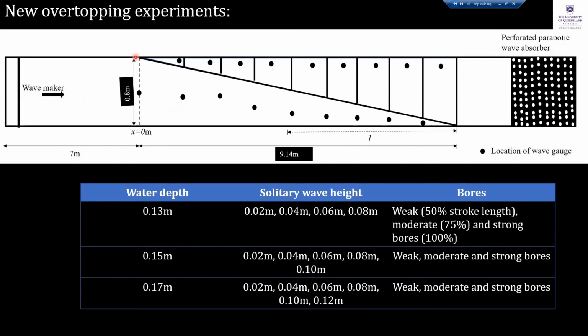So let's say this is a river wall that is going from one side of the flume to the other side. That is 20 centimeters in height. So once the wave is going towards the end of the river wall, then the wave would be overtopping into these small compartments. These compartments are just made by PVC sheets from the supporting sidewall.